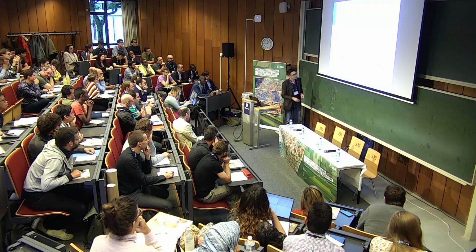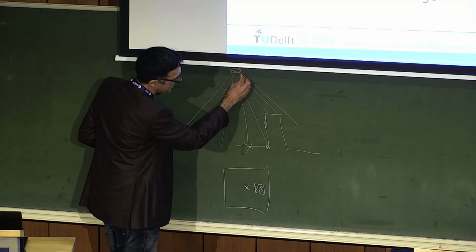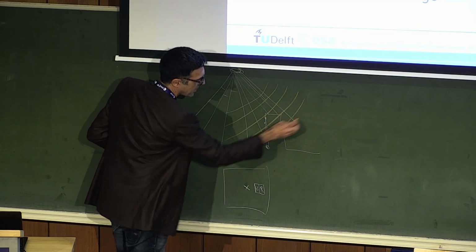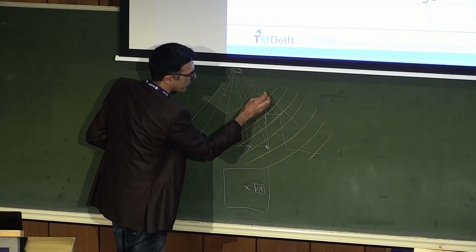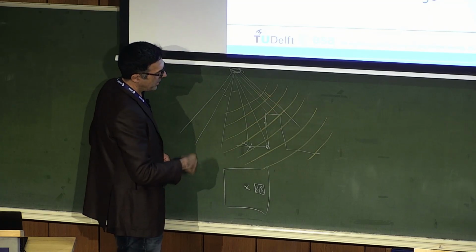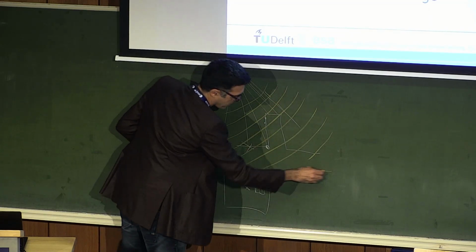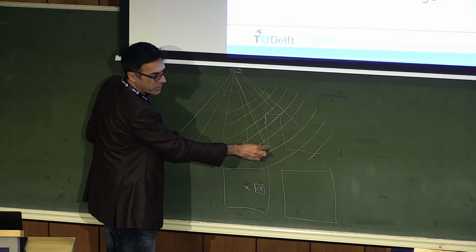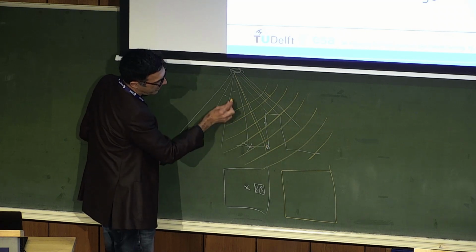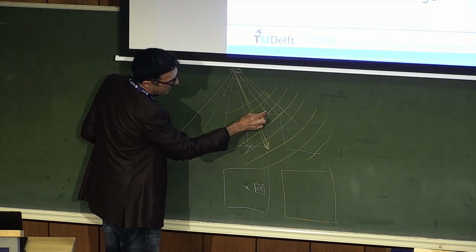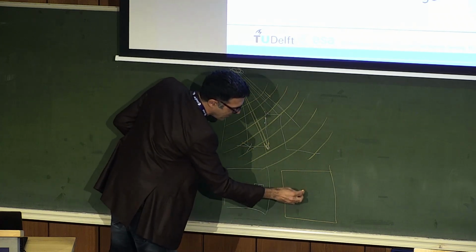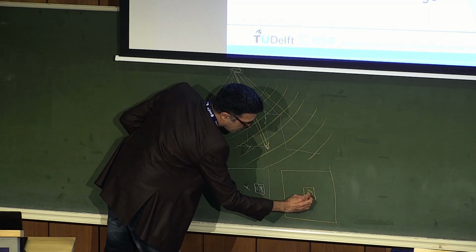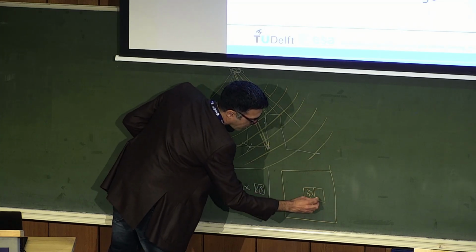Now, radar is side-looking, but the radar has these kind of areas of same distance. So now, instead of the same angles, we have all these distances which are all equal. And now you see that for a radar image, if I would draw that over here, and I'm starting, for example, over here. The foot of the building is further away in the radar. It has this range here, more than the top of the building. Sorry, I'm messing it up. So a roof of the building would be here, and it would be falling, let's say, towards me.